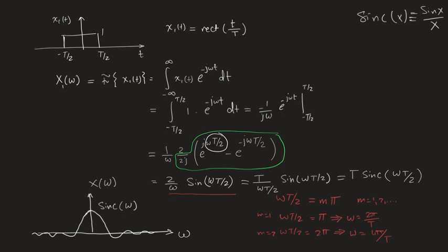That abrupt stop means that something in the time domain happened within almost 0 time. Something that happened with very high speed means that there is some very high frequency component in that signal, because of that abrupt stop at some point. That's why any time limited signal will result in a frequency domain representation that goes all the way to infinity, because it will always contain a very high frequency component due to the discontinuity at the point where it just decided to be 0 and stop there, okay?